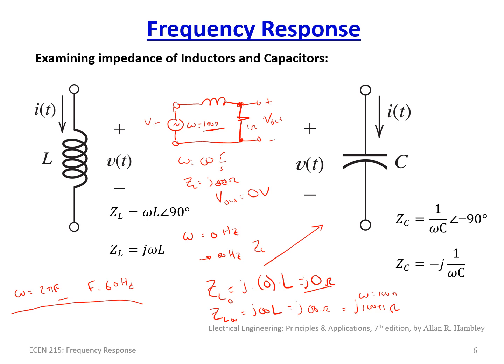So if we came over here just off to the side, and we made a little plot of V out over V in, we would see something that looked like this. We would end up with a signal that was decaying. This is V out over V in, where this is omega. So V out starts out at full voltage, but as frequency increases to infinity, we end up being 0. So that's fun to me.